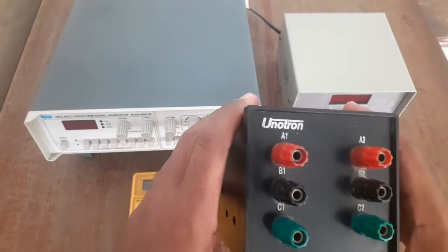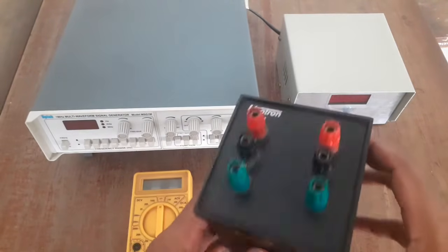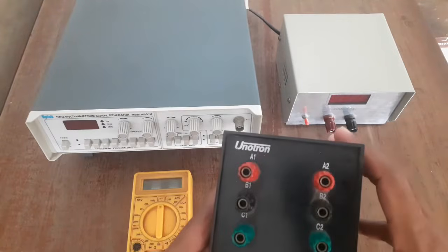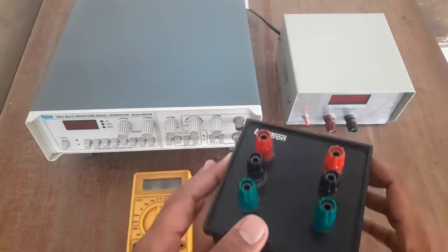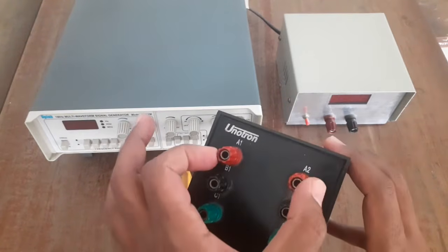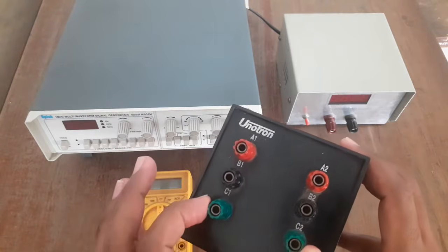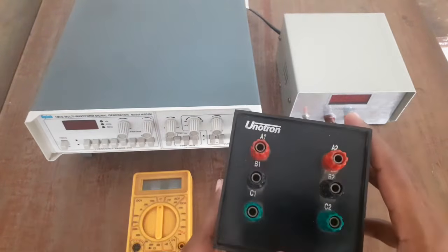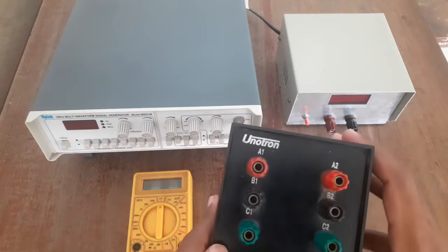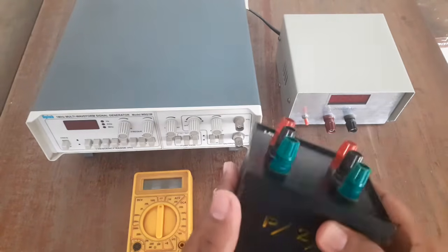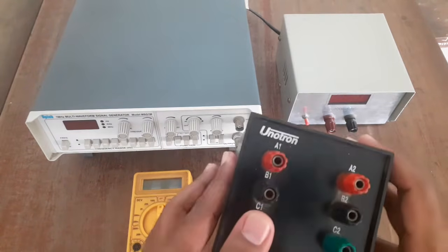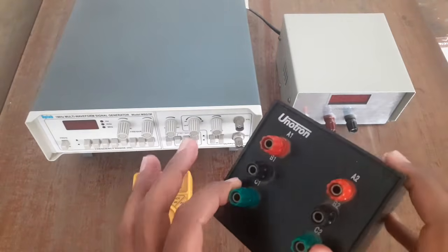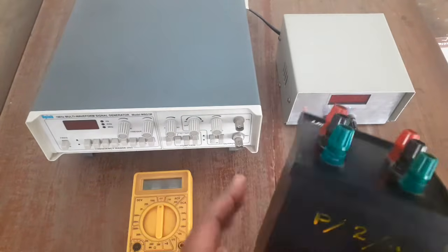It may be a resistor, it may be an inductor, or it may be a capacitor. By doing an experiment, we should figure out which component is connected across which of these terminals. As well, we have to find out the component value of it. Meaning if it is a resistor, how many ohms or kilo ohms it is. If it is an inductor, how many Henry it is. Or if it is a capacitor, how many Farad it is, you have to find out.